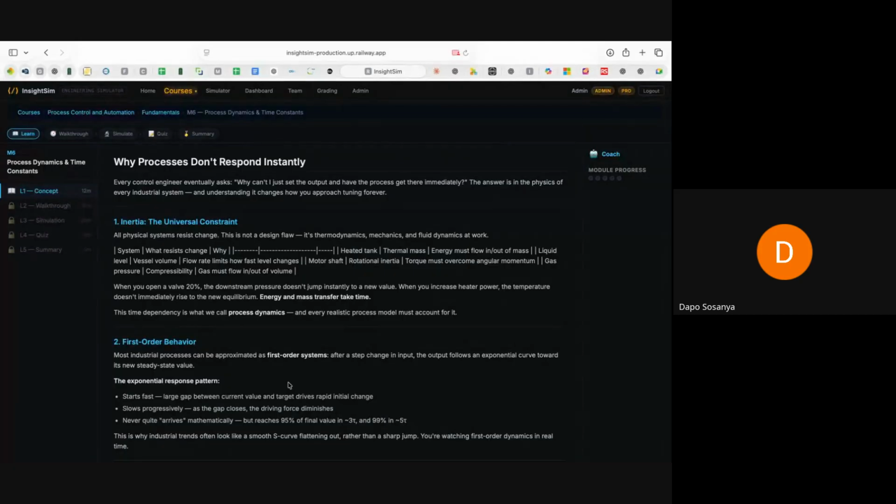The implication is this. You know that once your PLC gets into a scan, once it starts reading the input, right? Let's assume that it reads a pressure transmitter or a pressure switch. That is the first thing on the rung, right? It reads that, and then there are 10 other sensors it needs to read before running the program. The first one it reads, if that first one changes within that scan time, it is going to ignore that change. Do you know?